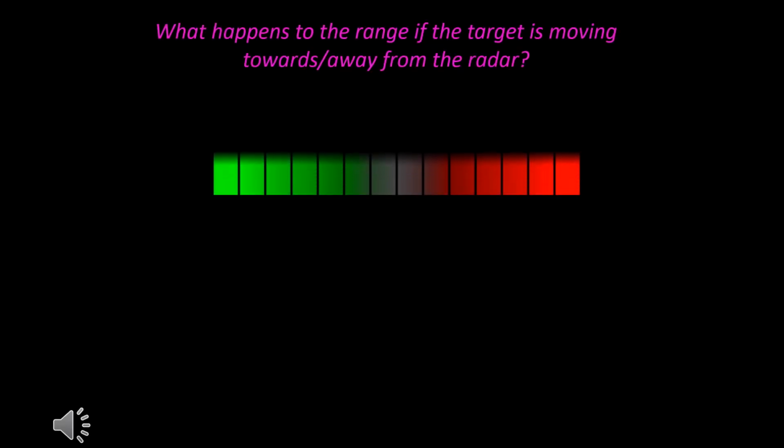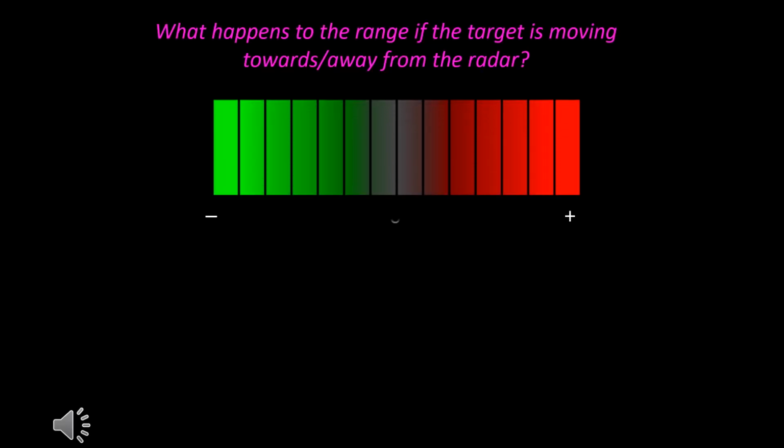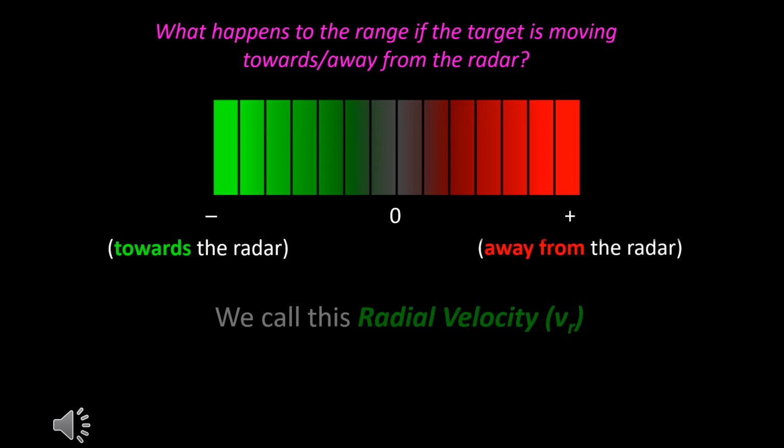Storms generally move from one location to another. Radar can be used to determine the direction and speed that storms are moving. Multiple pulses will be sent toward an object. By measuring how quickly the distance and position of the object changes, the speed and direction can be calculated. The measure of speed and direction is referred to as the radial velocity of the target.